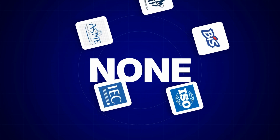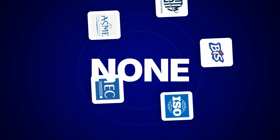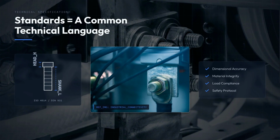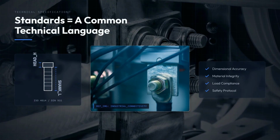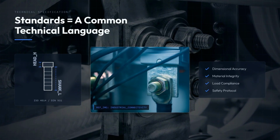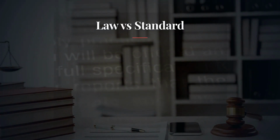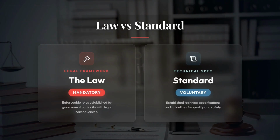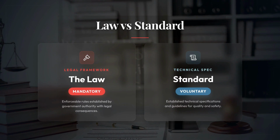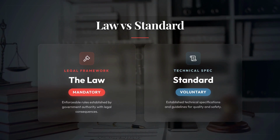There is no global ranking. They operate at different levels and solve different engineering problems. Standards create a common technical language. They define requirements for dimensions, materials, safety, testing, and quality systems. Without them, a bolt from one country might not fit a nut from another. Remember, a standard is not automatically a law. Most are voluntary when published. They become mandatory only when referenced by national legislation, technical regulations, or specific contracts.